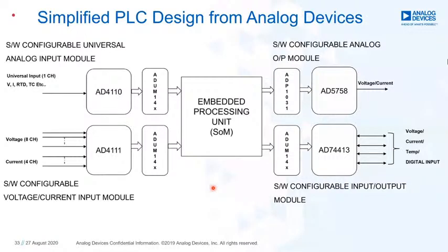Rather than isolating the signal, we bring in digital isolation. When I say digital isolation, the isolation comes after the ADC. So you will have an ADC or DAC communicating over I2C or SPI. There you are not losing any linearity because you have not introduced any components in the front end which play with your linearity, like an optocoupler.